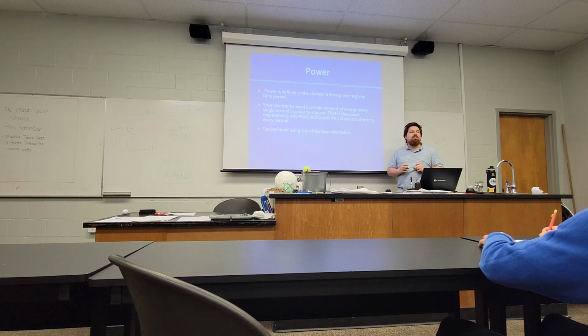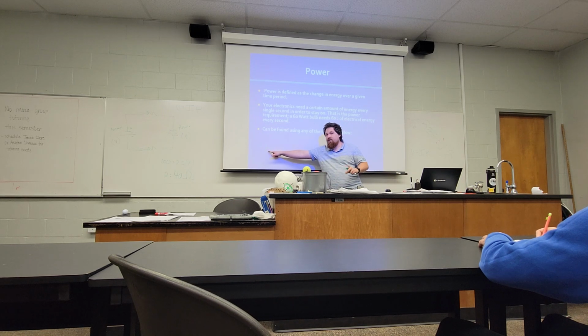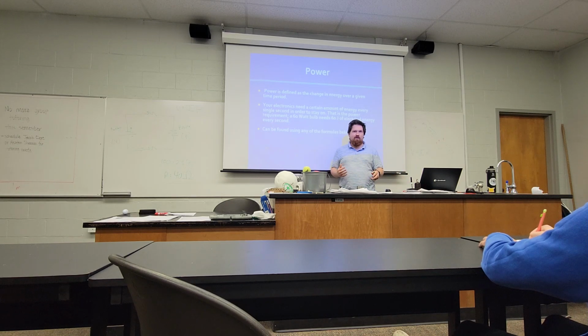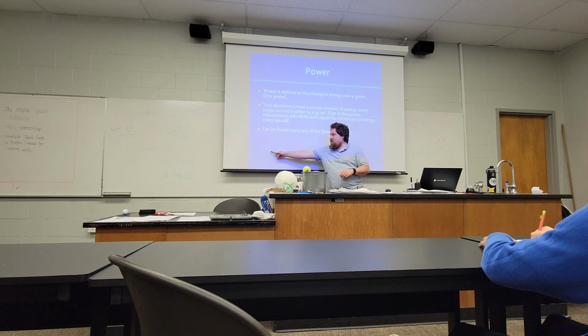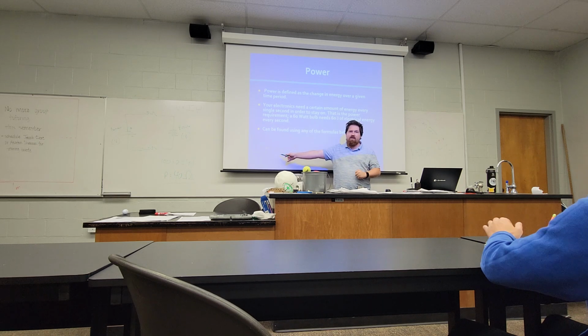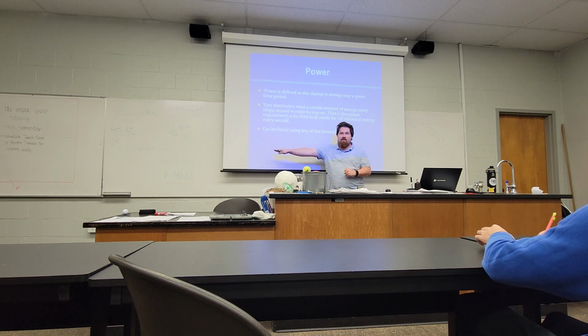Now the way to determine the wattage of something, there's a couple related formulas here for electrical power. Power is still capital P, and power is still work over time. That's still true, that didn't change. These are extra formulas for the electrical version of power. The power a device needs is equal to its current requirement times its voltage requirement. Current tells you again how many electrons need to pass through it every second. Voltage tells you how much electrical pressure is needed to push that current through it. If you know these two requirements of a device, you can figure out its power rating.